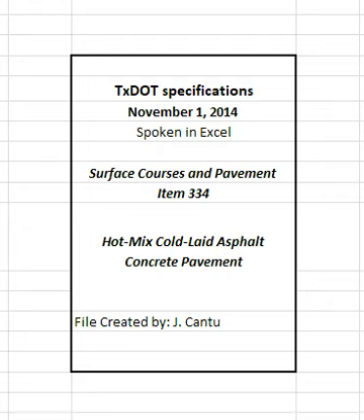4.2 Production operations. Perform a new trial batch when the plant or plant location is changed. Take corrective action and obtain approval to proceed after any production suspension for non-compliance to the specification.